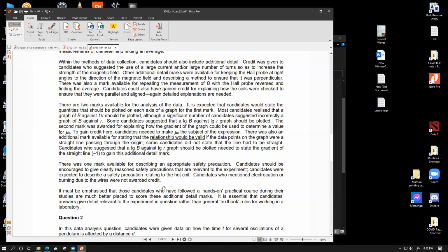Yeah, electrocution is not going to happen over here because we are doing our experiment with a DC supply with a very significantly low voltage, so you're not going to get electrocuted. I mean, that's just not going to happen. In the worst case scenario, you're going to feel the heat of the temperature, but the resistance of your skin is too high for DC voltage to pass through.